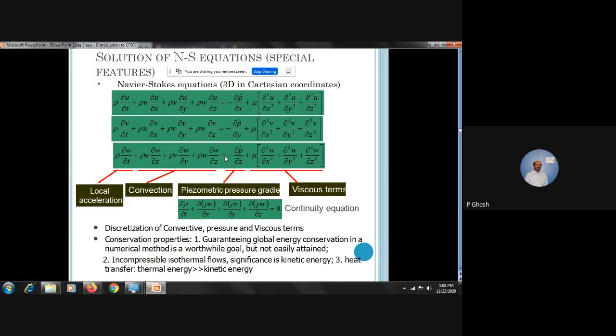We also have coupling, because obviously u alone will not give you the solution. You see the unknowns are u, v, omega, and p, because the properties etc. are known. So there are 3 equations and 4 unknowns. u is one unknown, v is another, omega is another, and p is another in that particular x, y, z in a fluid domain. So you have 4 unknowns and 3 equations. What will you do? You have to introduce an equation.